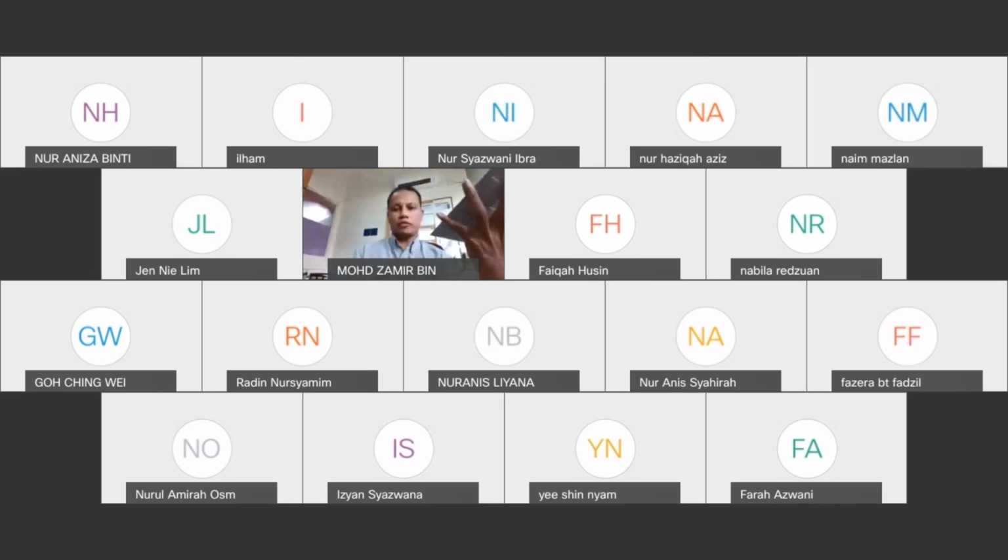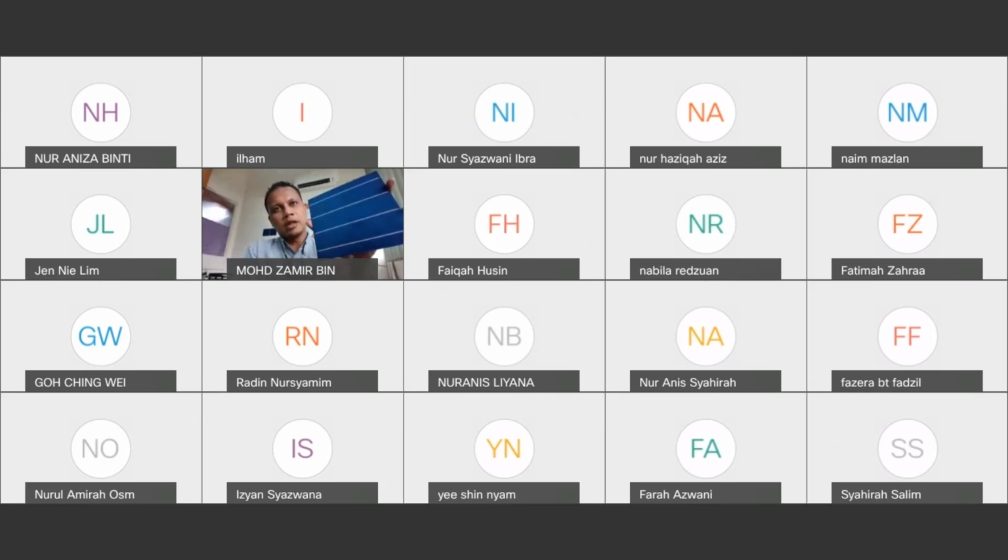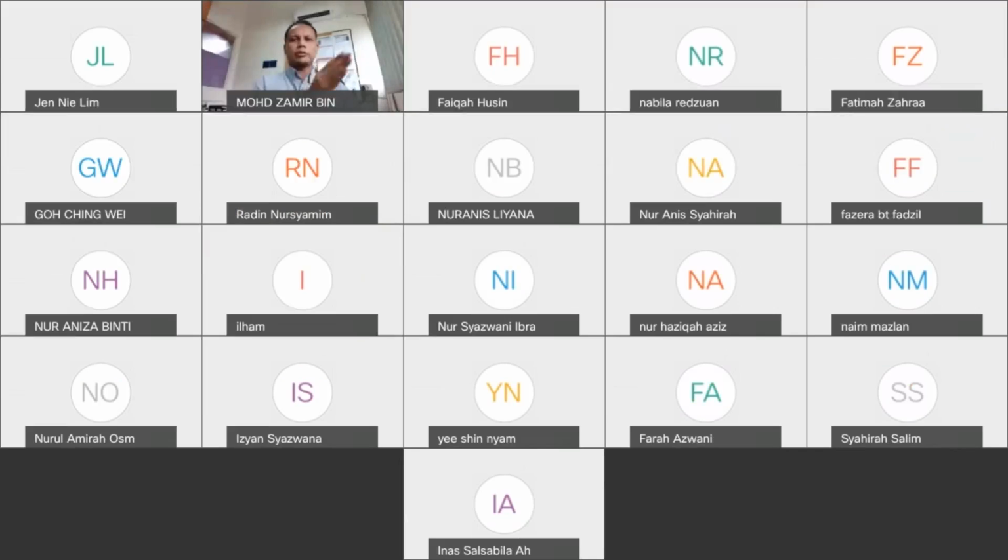They look uniformly blue. The blue color here on the silicon belongs to a silicon nitride thin layer coating, or we call it ARC, anti-reflective coating, that we learned last time from 386 when we did device presentation. It's about 75 nanometer of silicon nitride. So it gives the silicon blue color because of the reflection in the short wavelength region between 300 to 500. This silicon wafer is originally gray in color before the solar cell fabrication.